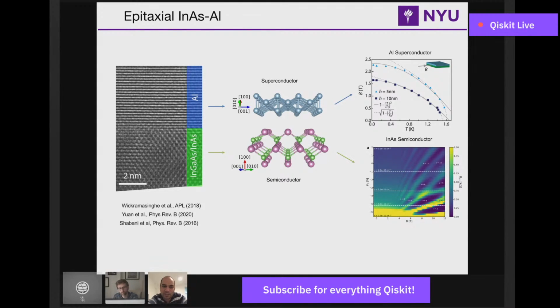I can grow a structure without aluminum, and I can grow a structure with aluminum and then remove it. What I usually find is that the one that has had the removal of aluminum, the density, for example at 0 gate voltage, is 10 to 20% higher than the ones that I don't grow aluminum on at all. I see. If you're not careful, it could actually be quite wild. But now with the optimized process, I think 20% is reasonable.